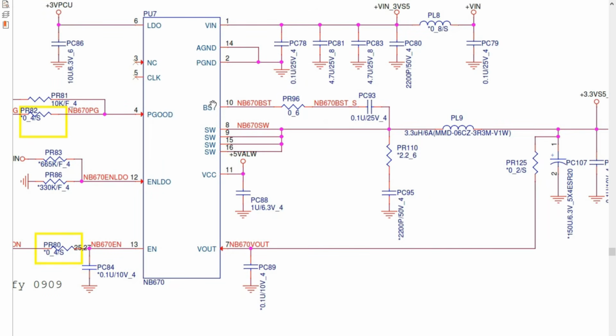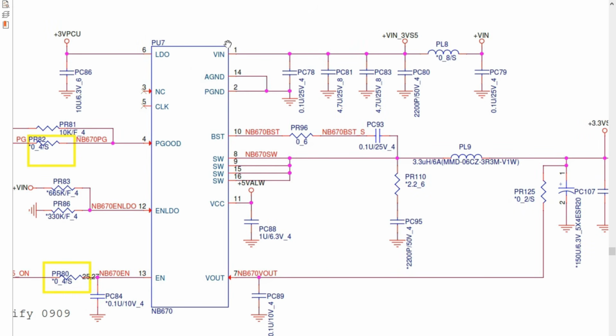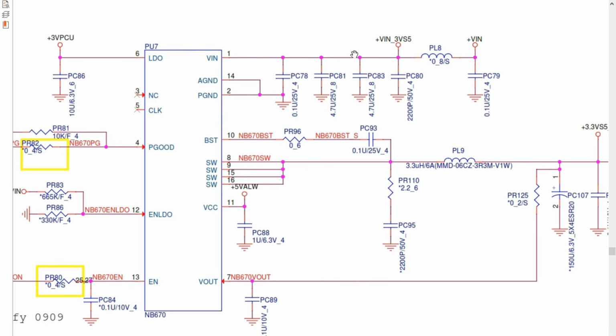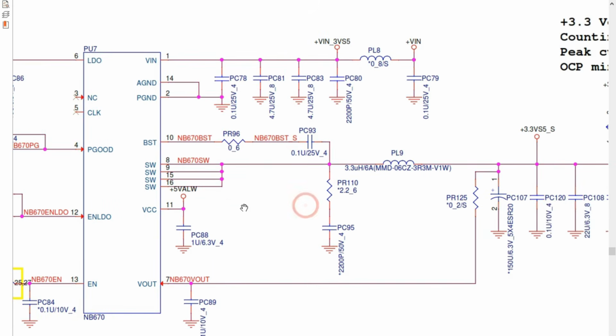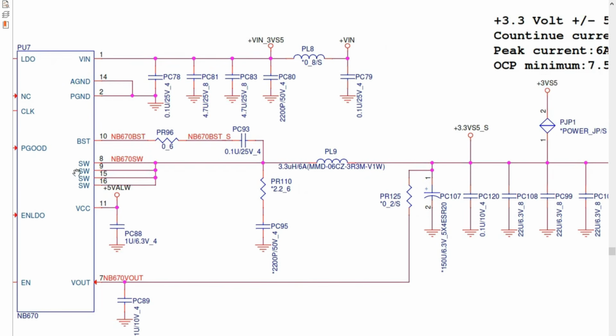And here of course we have the boost, we have the VCC plus 5 volt, we have the VOUT, but the important inputs are VIN, power good, and enable signals. For these two pins, we have this mark here, which means no connection, as you can see, NC means no connection. So after receiving the 19 volt and all these enable signals, the IC can generate this 3 volts.